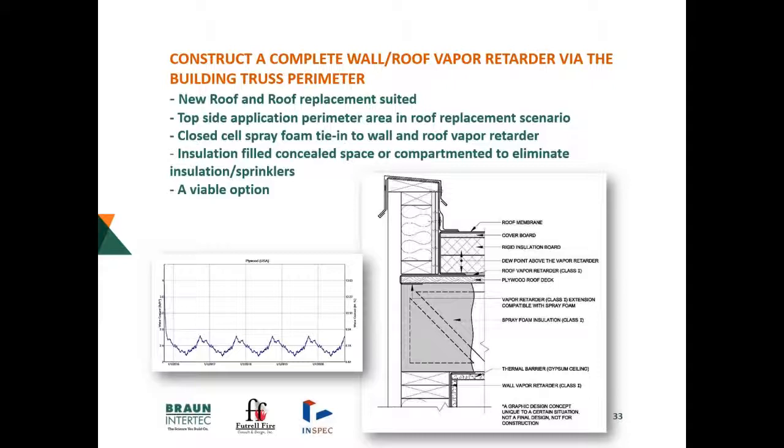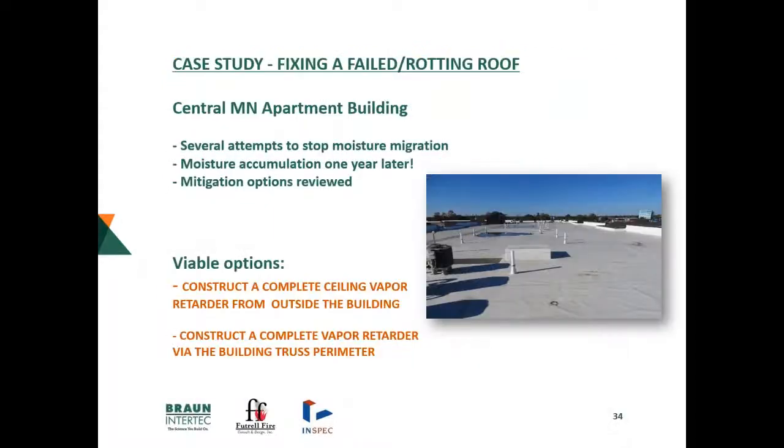But now you've got this bridge and this continuousness around the perimeter, which takes care of being able to draw a line continually, not lifting your pen, from the wall vapor retarder up along the leading edge of the spray foam, and then up into a connecting membrane. We've got a membrane coming around the plywood deck there. That's one concept, and then that connects to the vapor retarder on the roof. We now have a complete vapor retarder.